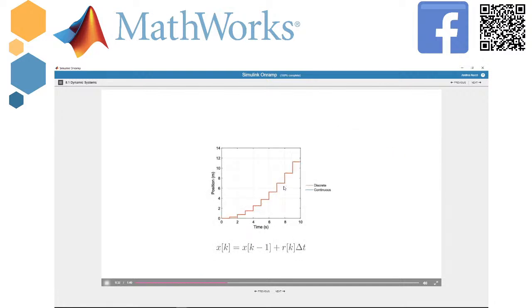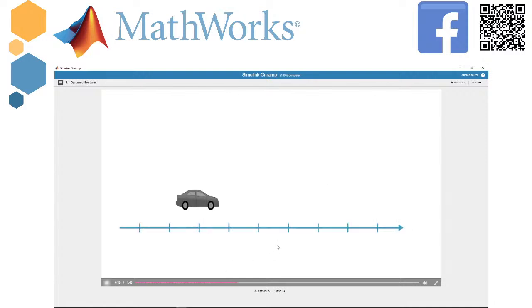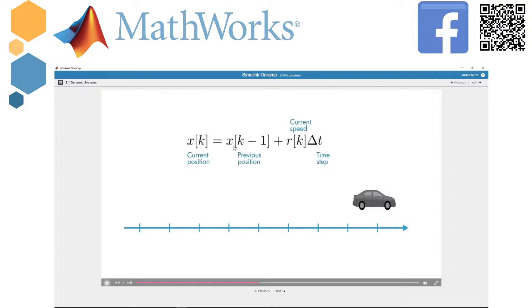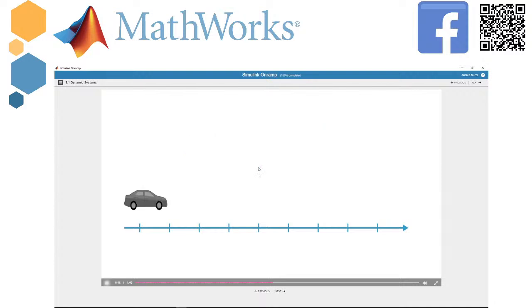That's good. Next, I can just double click the unit delay block and set the sample time to 0.5. Run the model and use the scope to compare the two signals. I will show you the sample time in a second. They usually have a sample time of -1, and if you want to change the sample time to 0.5, for instance, you properly add a sample time.